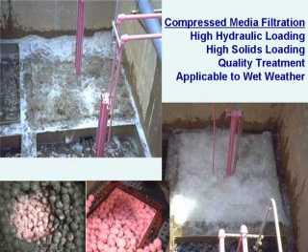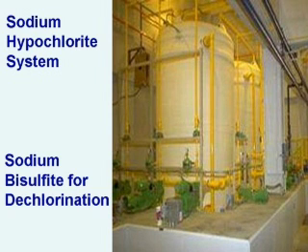We have those pumps; they have hardened impellers, and they're very rugged, but they take all of the abuse, and this is where most of the maintenance of this facility is, and that's probably true for all these kinds of facilities. You get sand; it wears down these types of pumps, and they have to be removed and wear rings replaced and retrofitted on a pretty regular basis. But for every pound of TSS we've measured going into the vortex systems, we've removed about 1.5 pounds of sand and gravel. So that tells you when you're measuring for TSS, you don't really measure everything that's going into a treatment system.